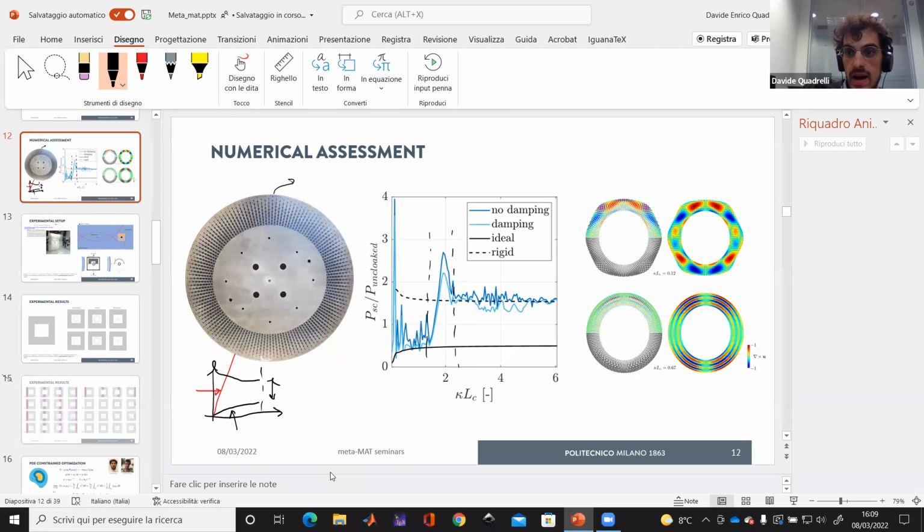And the only way I can explain this is that when I look at the real dispersion relation, I'm thinking of an infinite material. But this is a finite size specimen. So the evanescent waves take a role, especially at the interface with the fluid, because the pressure field outside should mathematically match on the boundary the field inside.